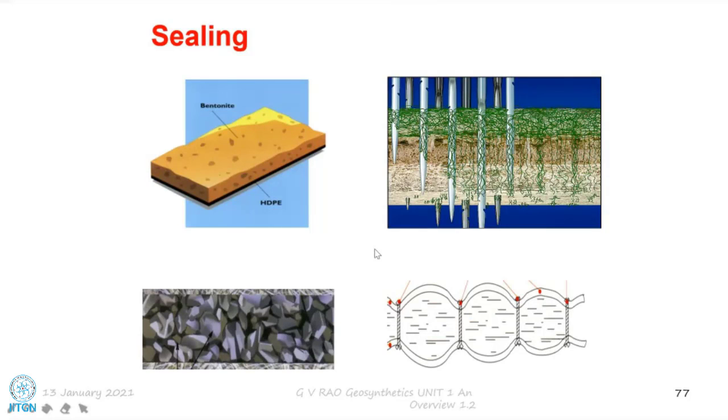So what is happening is that once you are stitching into this, once you are needle punching into this, we already said that the fine fibers are getting entangled into this. They are the ones which are binding this. The needle punching is going to help in binding the entire thing. So there is a kind of tacking. Multiple stitching is going to cause an implication like this. So sometimes people prefer needle punching. This is actually stitch bonding, multiple stitches. And here, of course, the pieces of bentonite, which are already in pellet kind of form, are placed, and then the suspension and other things are going to be a requirement.